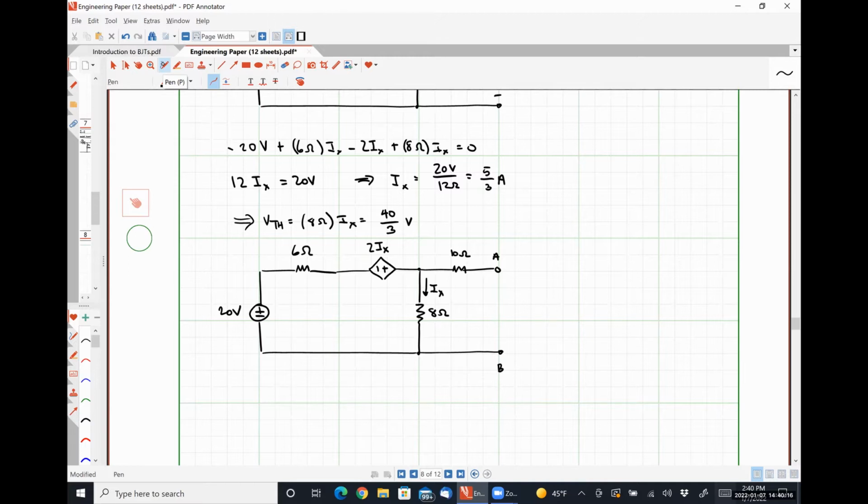Carter, were you scratching your head or raising your hand? Short circuit A and B. And then we measure the current in the short circuit. And because we found the Thevenin voltage with the positive polarity on top, our Norton current should be directed down. So, Brittany, I haven't seen you in a while, so I'll pick on you. What circuit analysis method would you care for us to use to determine the quantity I Norton in this circuit?